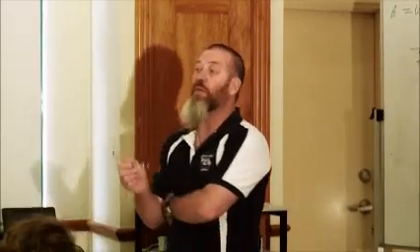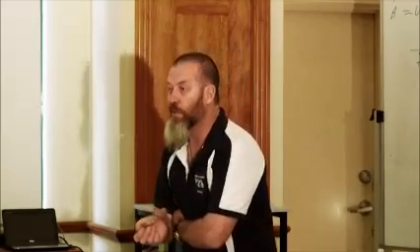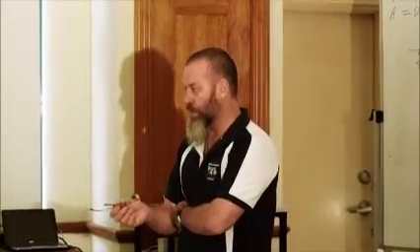Now I just said to you about the mechanical grading system, MGPs. Computers control MGP systems, not human beings. All your F gradings and everything else is visual stress grading. So they can look at a piece of timber and they can look at the end grain of it and determine whether it's got heart in it or not. A computer can't do that yet. It will get there, believe me. So what we want you guys to assume is that every piece of pine you're going to use, because would I be right in saying the majority use MGP? Okay, as your framing, assume it's got heart in it.